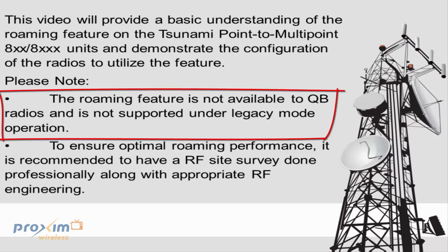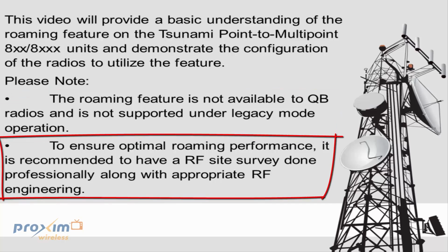Please note, the roaming feature is not available on the QuickBridge radios and is not supported under the legacy mode operation. Also, to ensure optimal roaming performance, it is recommended to have a RF site survey done professionally along with appropriate RF engineering.